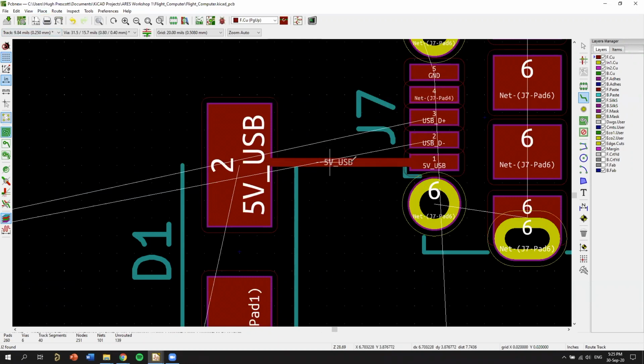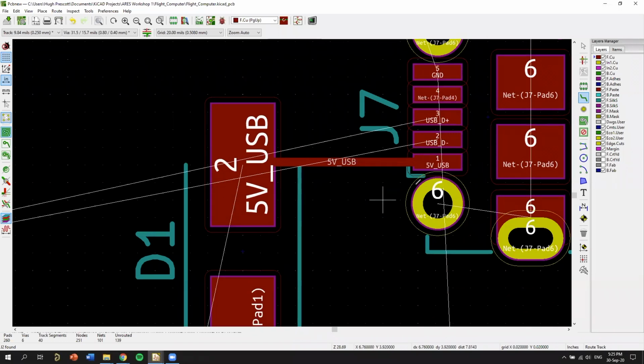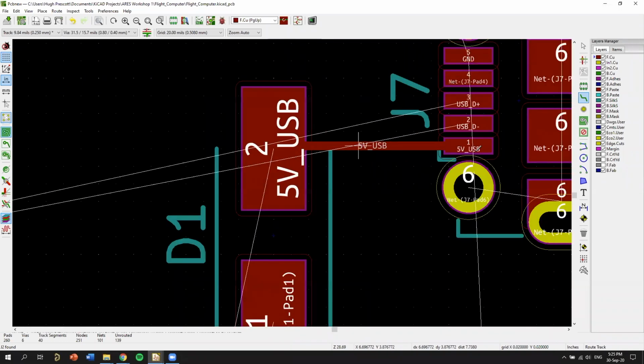If you have higher current, you normally want a thicker trace to handle the current, primarily because I think the thinner the trace, the more inductance it has or something like that. If you're trying to push a lot of current through a very small trace, it's going to heat up a lot. So the wider the trace, the better the thermal properties as well. It'll be able to dissipate more heat.